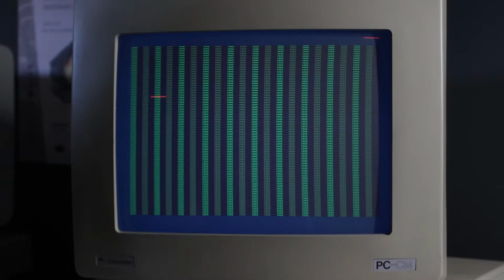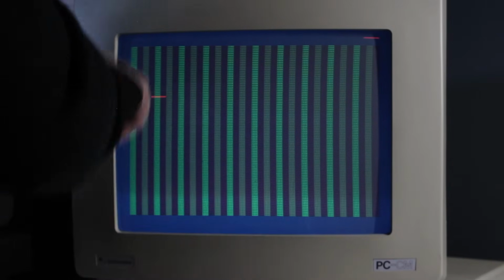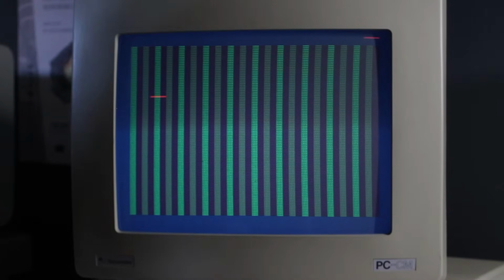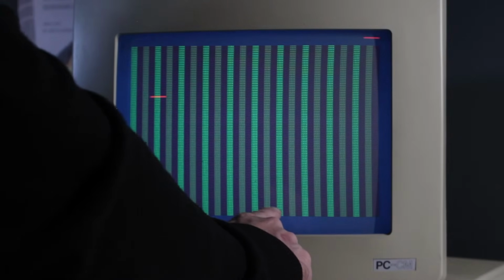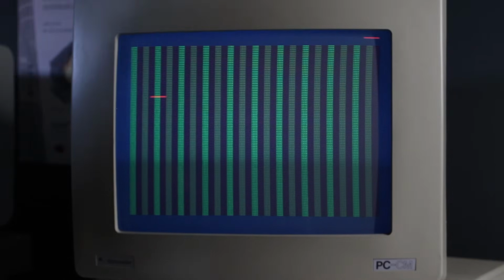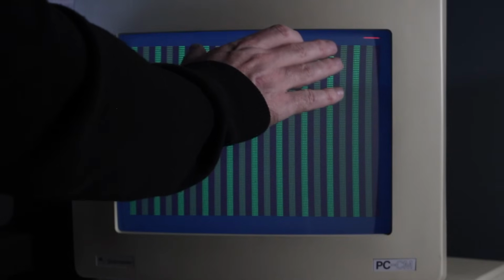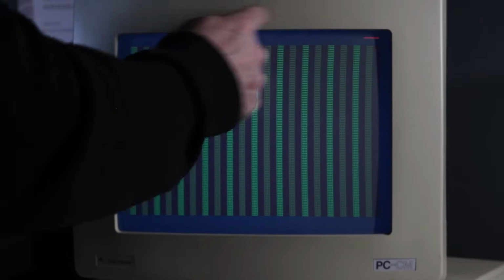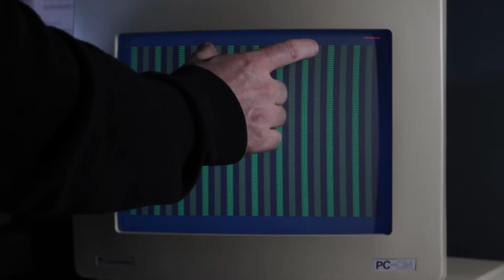So instead, what I've done is I've polled the status bit for the vertical retrace, which only happens once a frame. And yeah, that's really slow because you could be here, and if you shift by 1 character every frame, there's a hell of a lot of characters to get you back to the beginning of the frame. So what I do is, first of all, I figure out roughly where the start of the frame is. And actually there's a really long CPU loop that does that. Each iteration takes quite a bit of time. So you never get exactly the start of the frame this way.